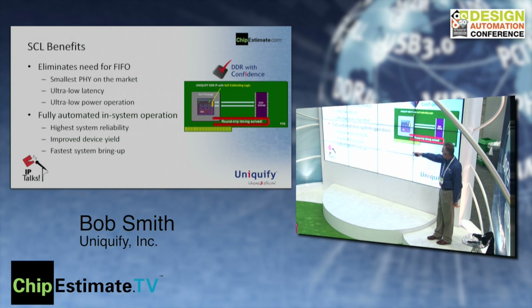The other thing I'll point out is the system bring-up is phenomenally fast. Most of the customers I've talked to, when they get that SOC back, get that DDR interface up in less than half a day. Because again, they're not having to sit there on the bench and try all kinds of different combinations. They program and say, go run this self-calibrating logic routine, and it will go off and find the optimal point for that interface.